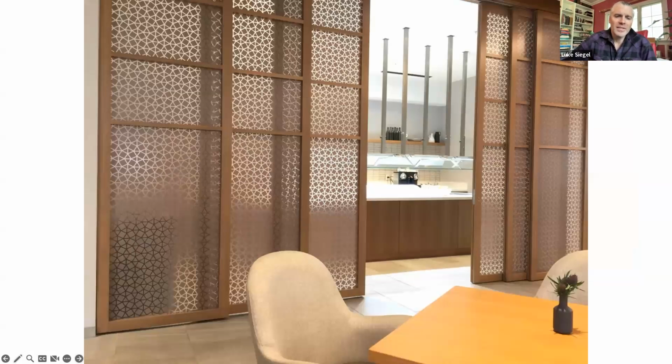A system like this is a 6-panel symmetrical sliding wall, fully floating, overhead suspended, probably 9 foot, 9'3", something like that, these panels. It's a custom stained maple with custom muntin pattern. And you can see that polycarbonate, that's actually an Eco Resin 3form, which is 40% recycled content and a Class A flame rated material.